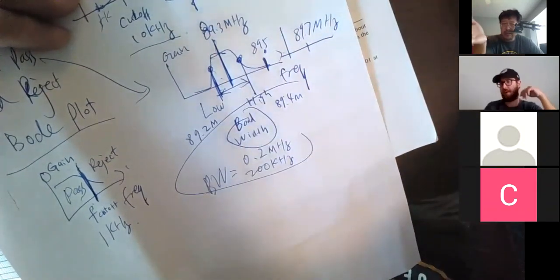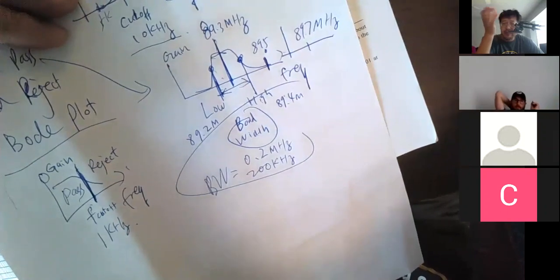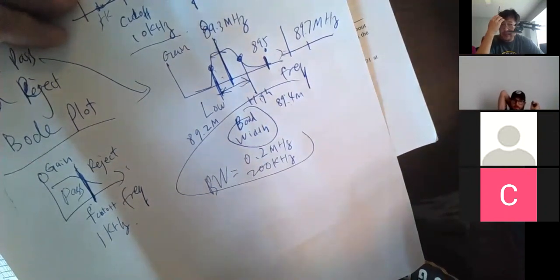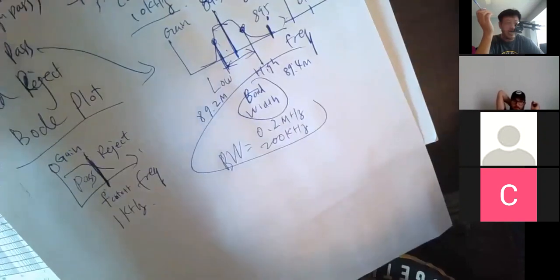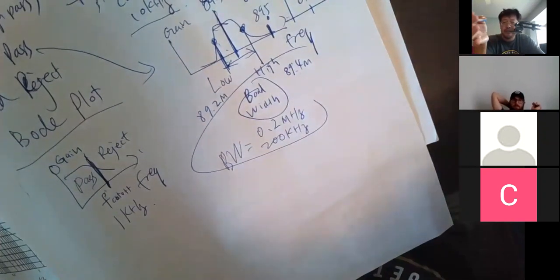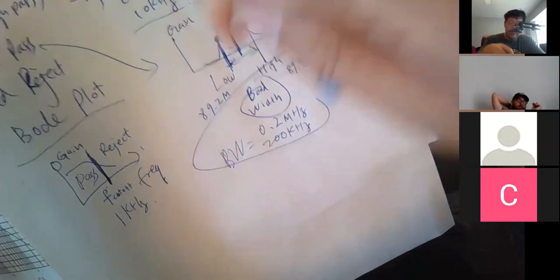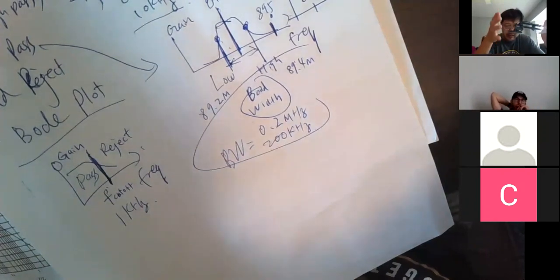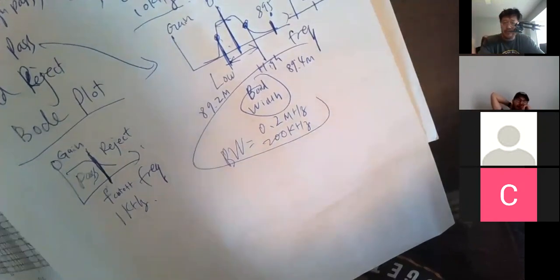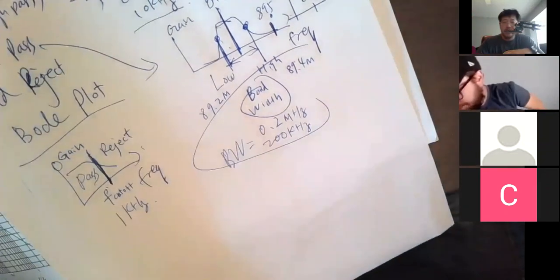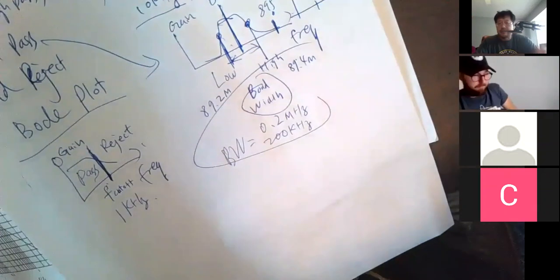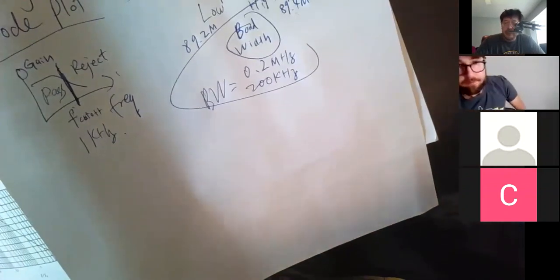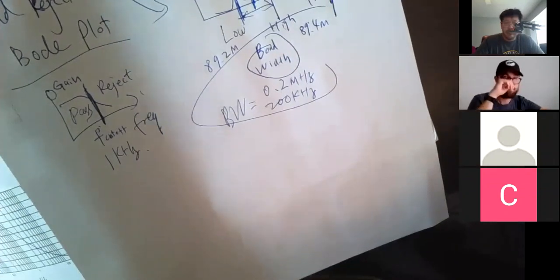And how do you do it? Use a bandpass filter. How many? You use it 10 times. Actually, if you look at a typical radio design, generally you have 10 of those filters because you really want to concentrate on one station. You don't want anything from neighbor stations. That's called a superhet radio. In previous semesters, we had a 342 class, a communication class, where we talk more about that. But anyway, that's a bandpass.